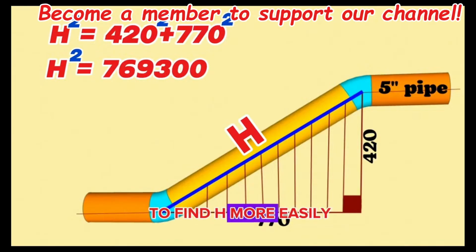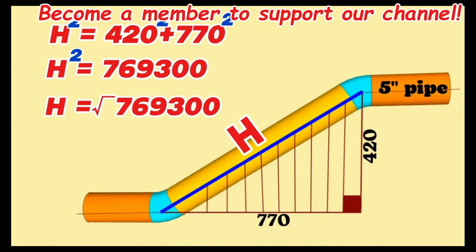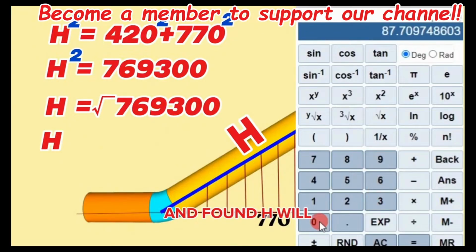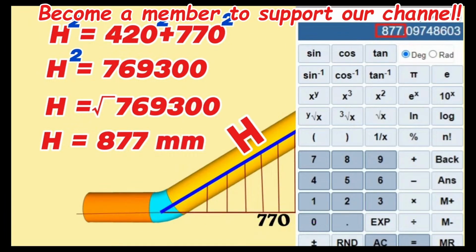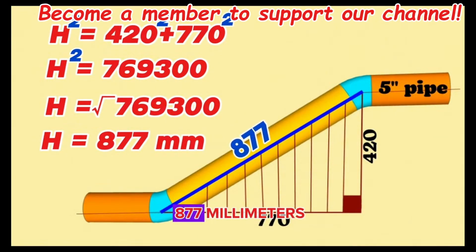To find H more easily, H will be equal to the square root of 769,300. Using a scientific calculator we found H will be equal to 877 millimeters. So, the overall length between the centers of the butt weld elbows is 877 millimeters.